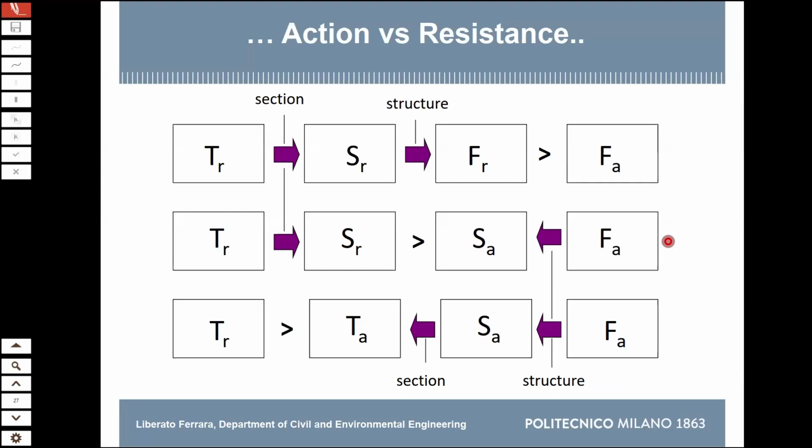We say there is the stress block, there is the yielding force and the lever arm, and calculate the resistance. Or we use a truss model to calculate the shear resistance. So resistance moment depends, but it's not the strength of the material. It's at a different, cross-sectional level.